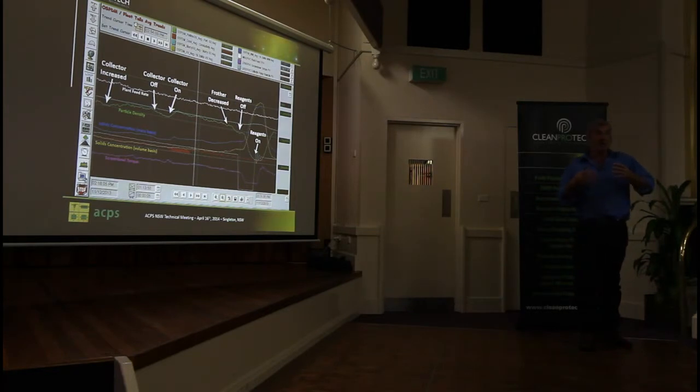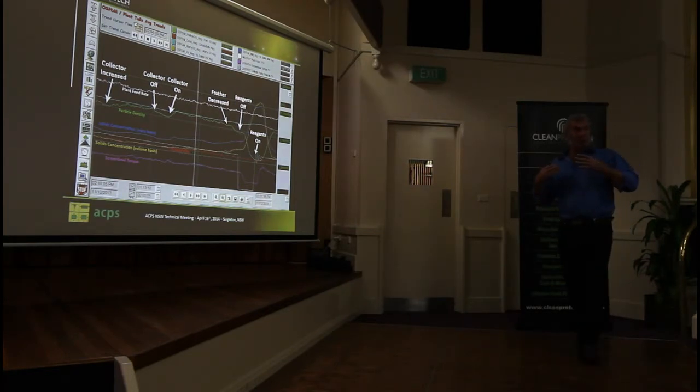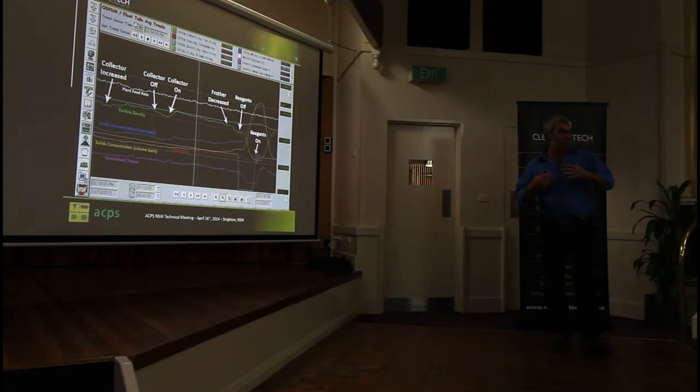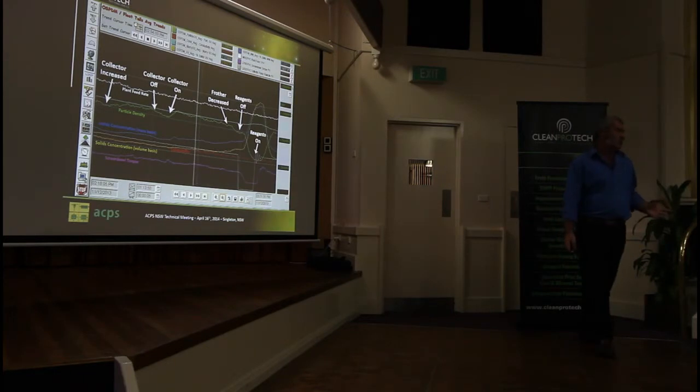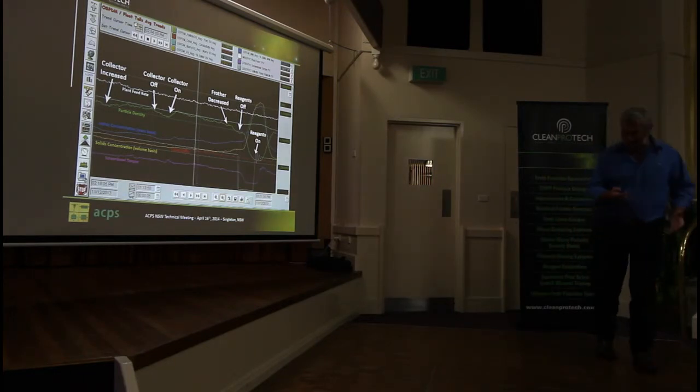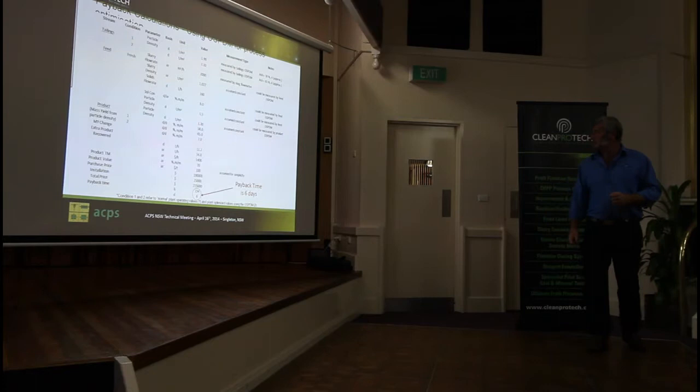It was just indicating that the feed had changed. There was more coal in the feed, but probably all the collector was being used. There was coal then going out in tailings and it wasn't being measured. And if you just looked at screen bolt torque, you'd never see it. That's some of the power, some of the things you get from measuring the tails.